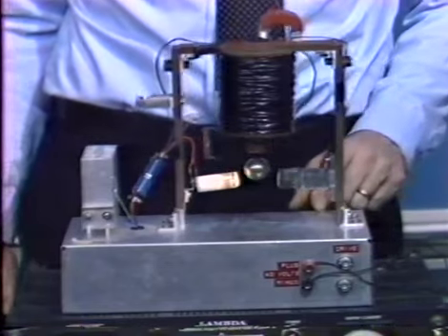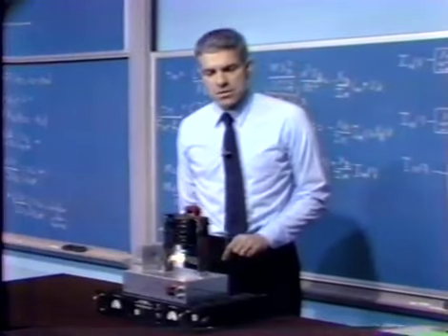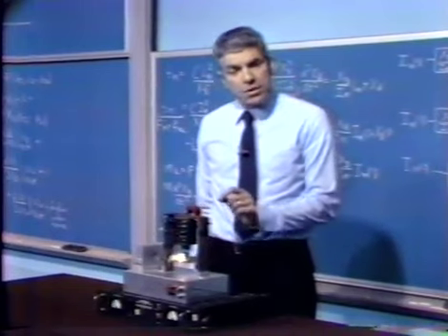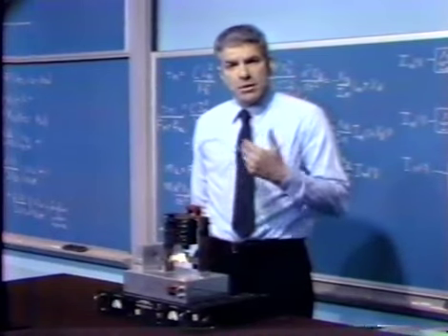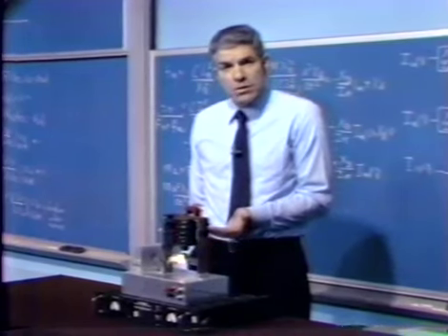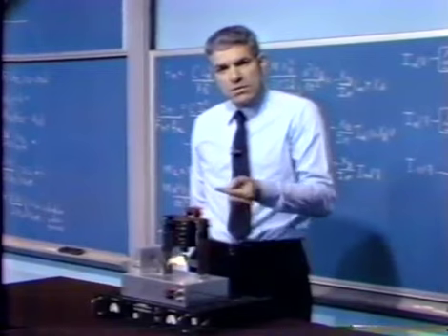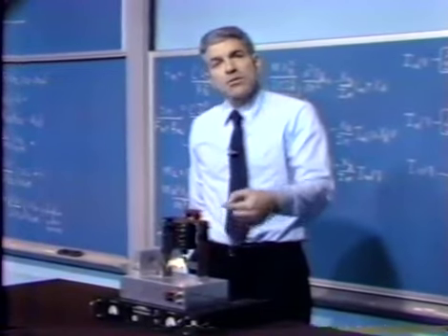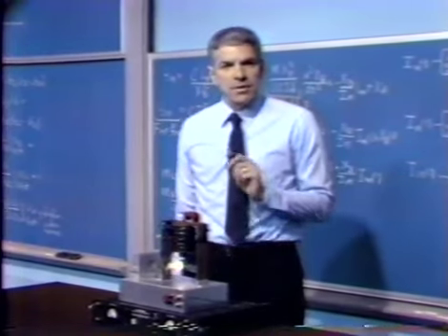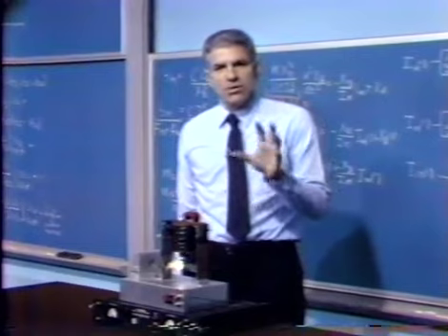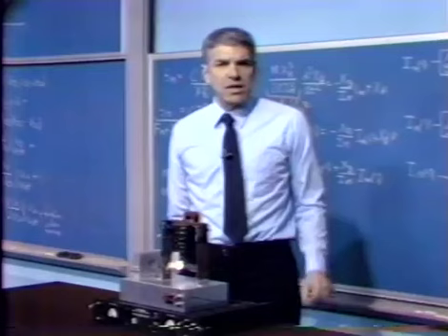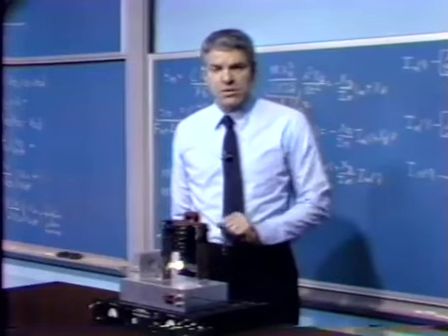So what we're now able to do is measure the step response of the system. The ball's in the magnetic field, we can perturb magnet current just a little bit, and the loop should react. If we increase magnet current, the ball will move a little bit closer to the magnet. As a consequence of that, the loop will react to lower magnet current to reestablish equilibrium. And we can observe the nature of that transient response. And it's the usual sort of wiggly, second-order looking kind of transient response that we've seen in a number of other systems, once the system's stable.